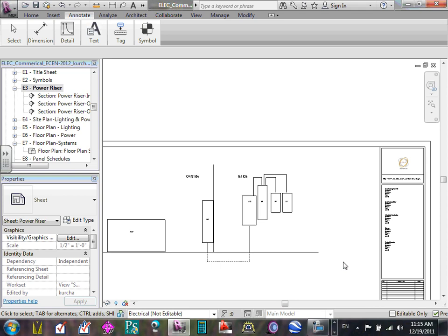Before you do the drafting, though, do me a favor. Make sure it's laid out really nice, because when you finish the drafting, if you move one panel, it will screw up your draft. Not a big deal, but make sure it's sized really nice. Like right now, see the panels are close to each other, I would move them, space them. But remember, every time you space them, you're physically mechanically moving them in the wall. You might run out of room in the wall. So when you move them, don't move them here. Did you guys hear me? With the panels, you see that close together, don't move them here. Go to the wall and move it. Because if you move them here, you don't know what's going on in the wall. You're going to go move in the wall.